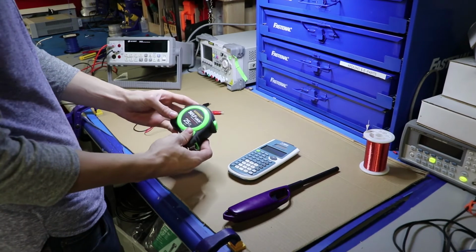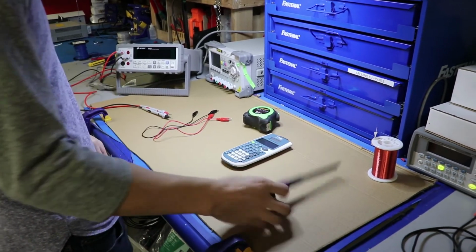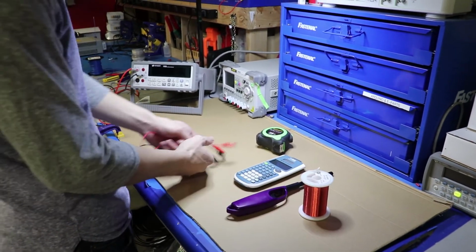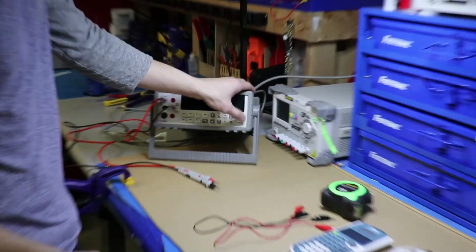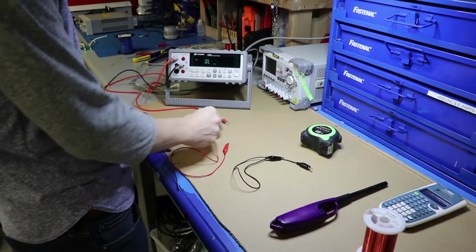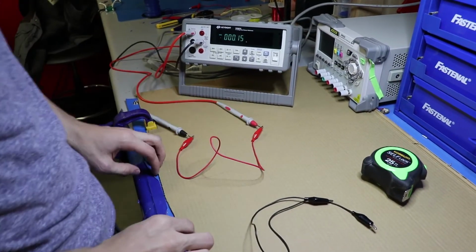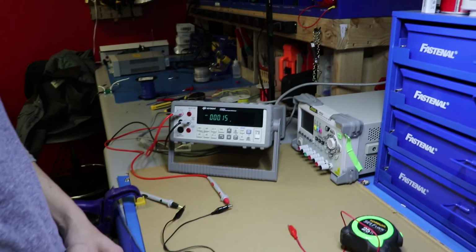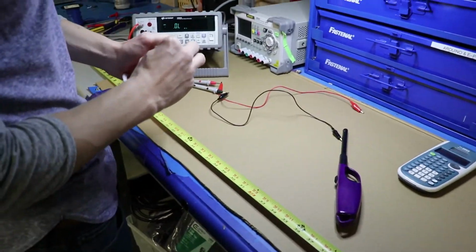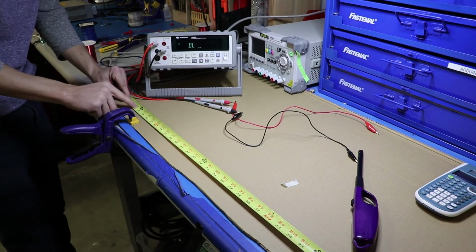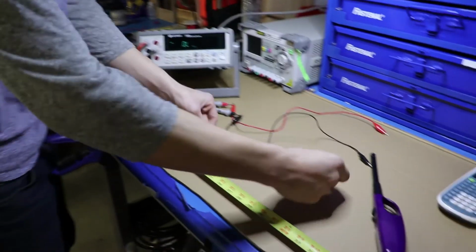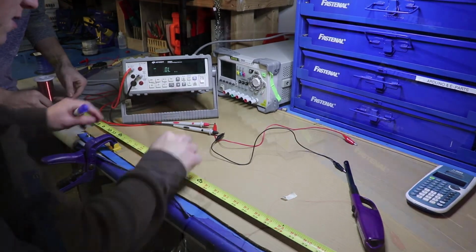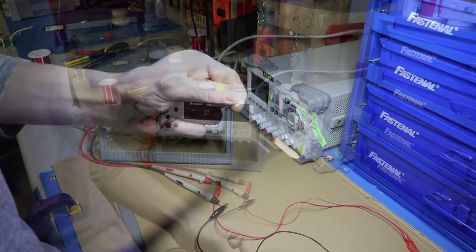For this experiment, we used one tape measure, a calculator, a barbecue lighter, some 42 AWG wire, 2 alligator clips, and one benchtop digital multimeter. So, we started by measuring the resistance in each of the alligator clips to account for any potential differences in our calculations. Then we cut off sections of wire in 1, 2, and 3 foot sections. In order to ensure good connection with the multimeter, we used the barbecue lighter to burn the enamel off the ends of each wire.